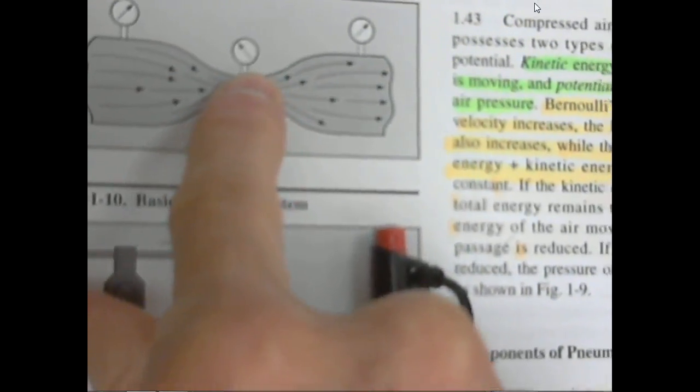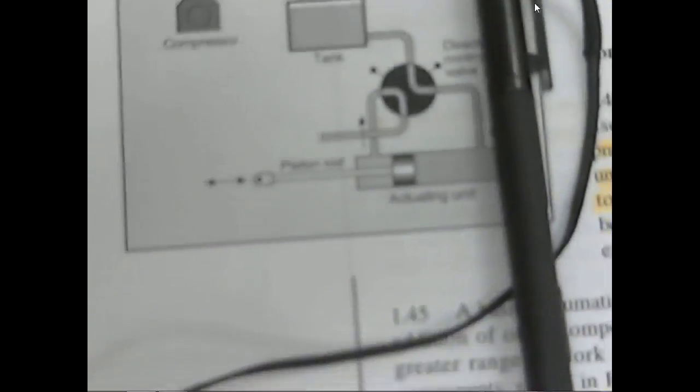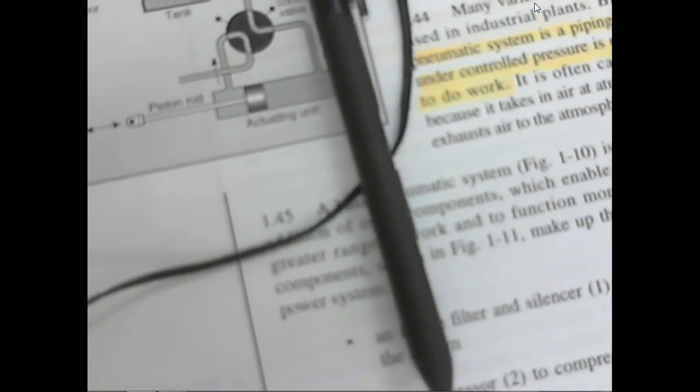Right here is where we tap off the vacuum. It's the same with a pressure washer: you put a liquid on there and run that liquid into the side of the Venturi. When you hit your pressure washer, it sucks that liquid right out of your bottle into the pressure washer, so you can add soap and all that kind of stuff.